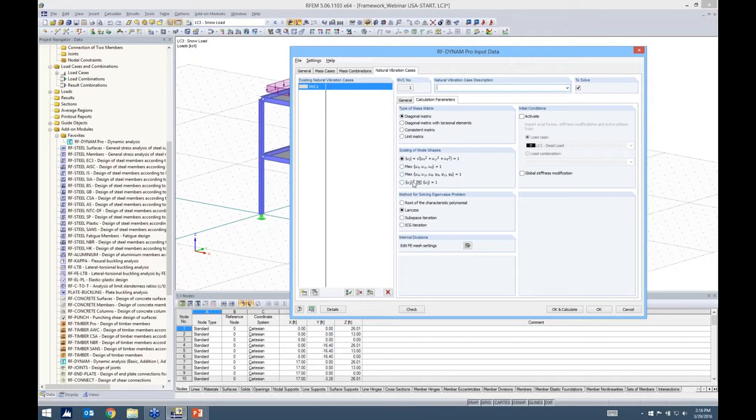This other option here, it's actually used internally for a response spectrum analysis and time history despite our selection of these 3. So keep that in mind that this is used internally anyway. This is where modal masses are set to 1 pound for each eigenvalue.